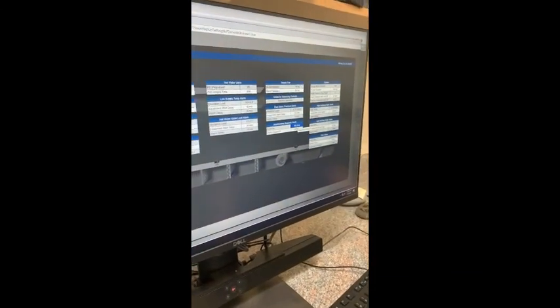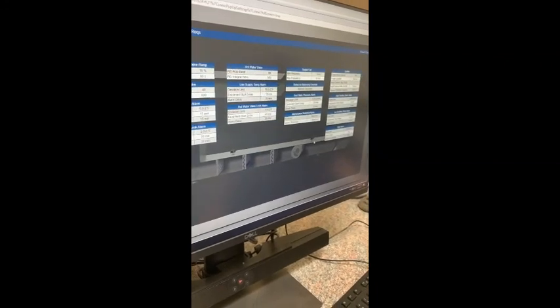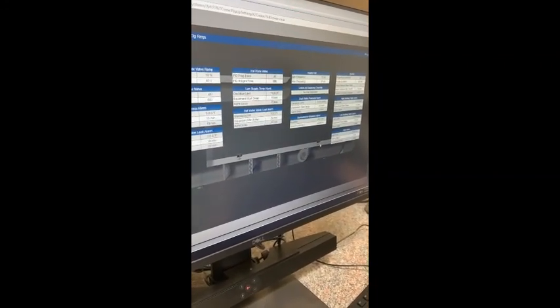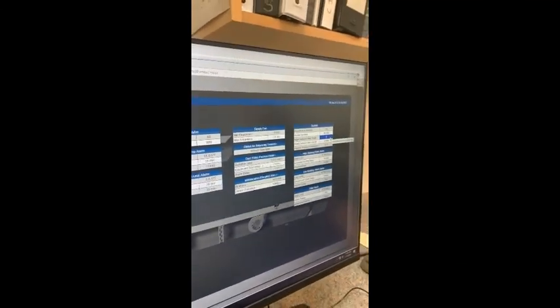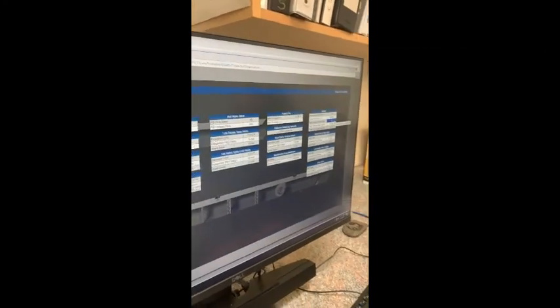Again, we have a maintenance reminder with its runtime and how many hours for that. We have the night setback requests. So if during the night two VAVs request heating, it would start the unit. Now, these ones never go unoccupied because of the IT rooms off of these, so it's really a moot point.